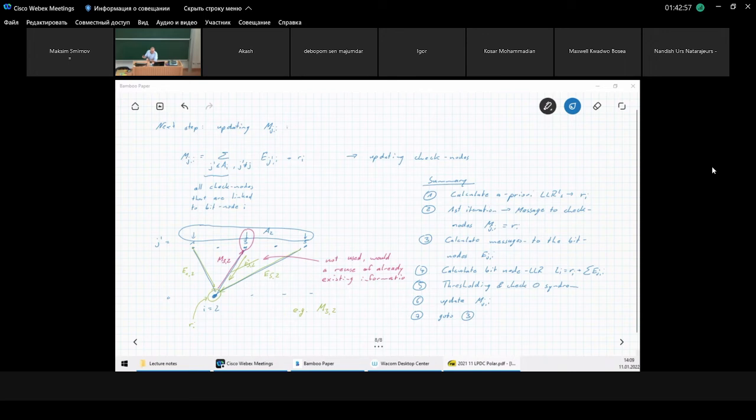Okay, so not very easy, I have to admit, but I think from the principle, it's not too difficult to understand. It's basically feeding back and forth information in this tanner graph using the fact that the bits are somehow linked together along the check nodes and exploiting this information to gain additional information on our observations. And this in an iterative way, thus improving our information.